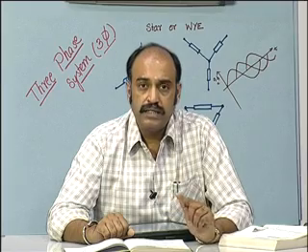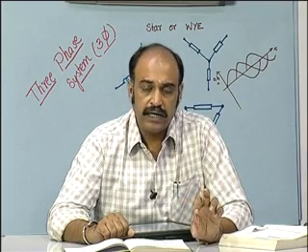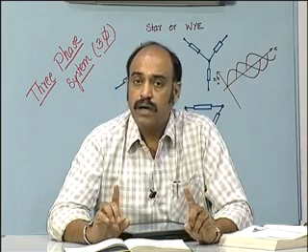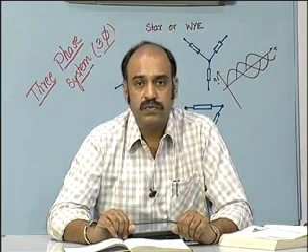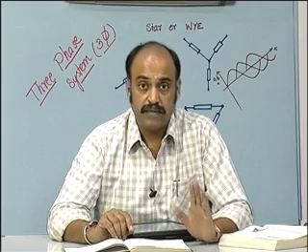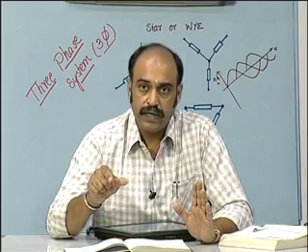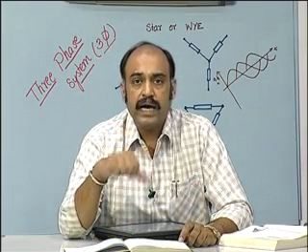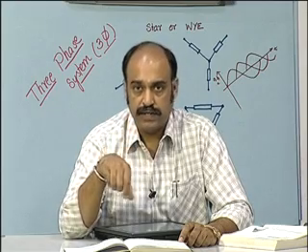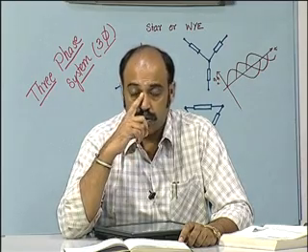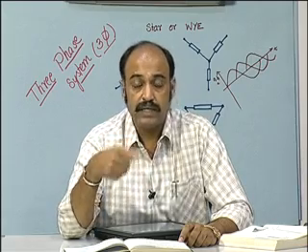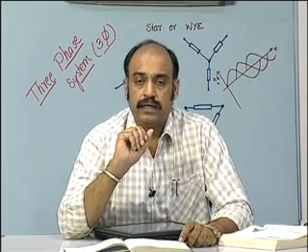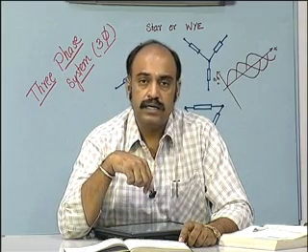In order to balance the line currents, that is, the line currents should have the same amplitude effective values, 120 degrees displaced from each other in the spatial coordinate system, we do a modification in the delta circuit by including two reactive loads in the other two phases. So, we have a resistive load, which is the active power drawn from the mains. It is still going to be only the active power drawn from the mains, but we add a capacitance and an inductance in the other two phases.